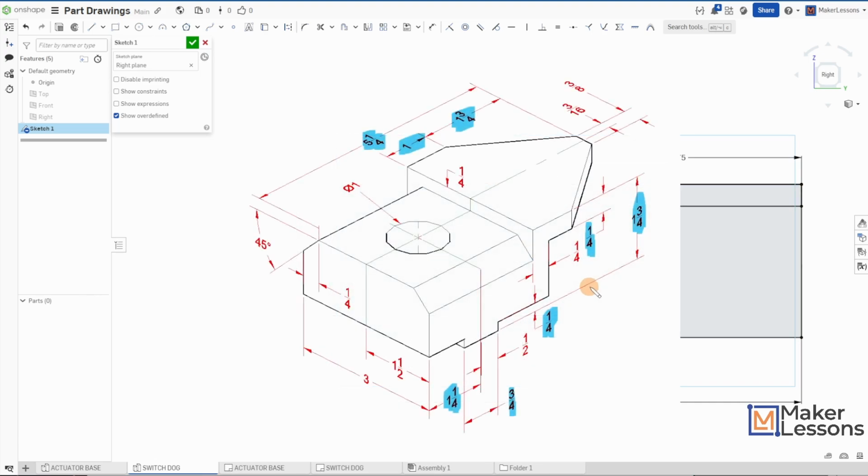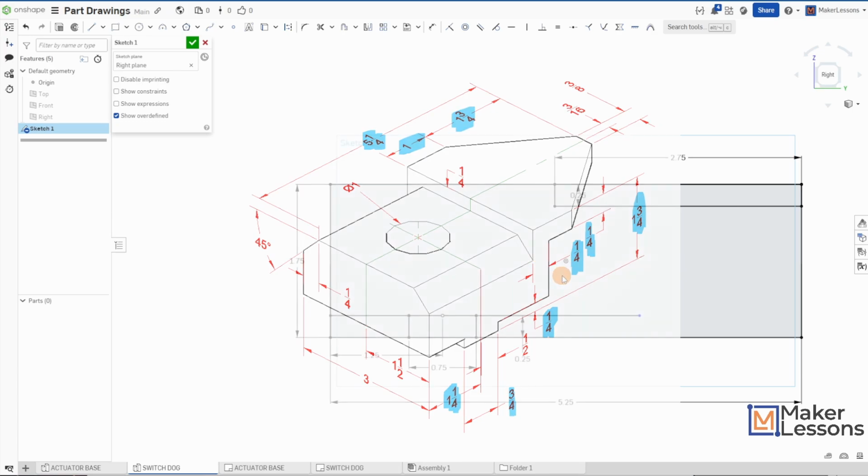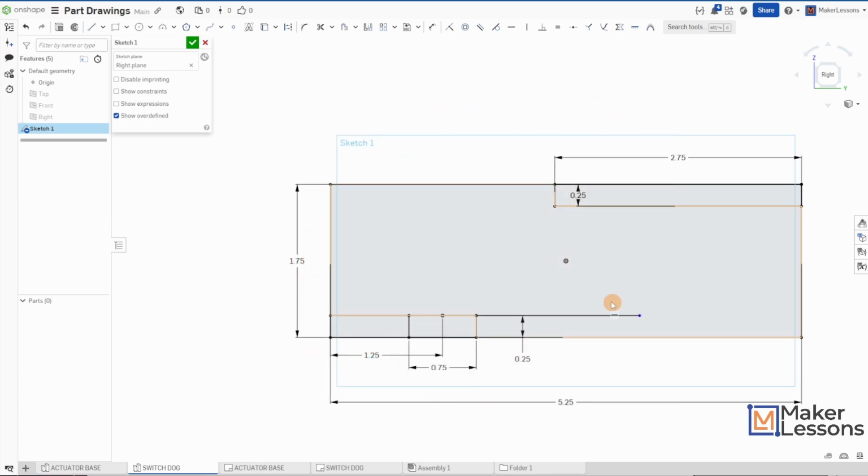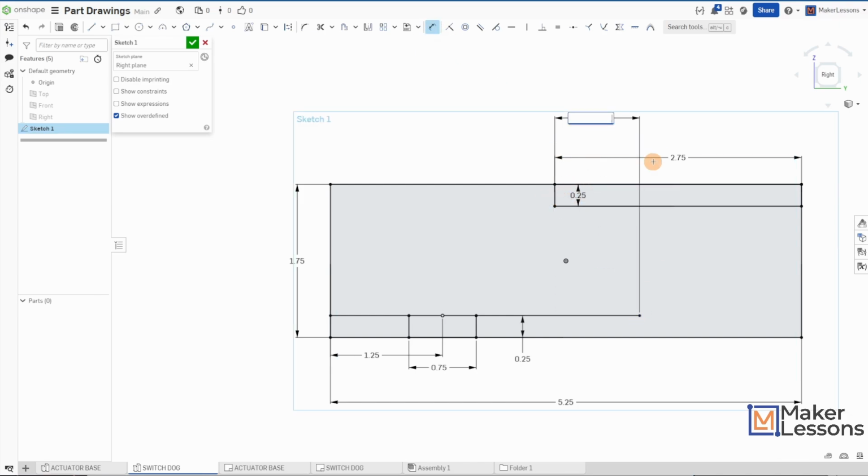Well, when you look at our drawing over here, this distance is 1/4 inch. So from the end of this point here to the back face here is going to be 0.25 inch. That leaves me with L for line, clickety clackety, escape on that straight line going up.